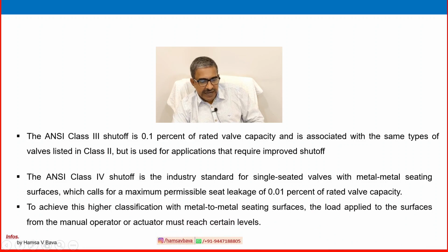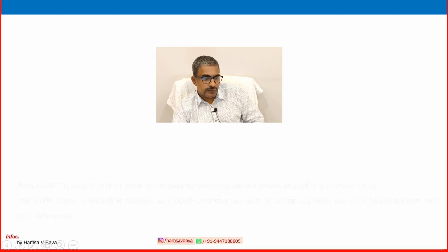To achieve this higher classification with metal to metal seating surface, the load applied to the surface from the manual operator or actuator must be at a certain level. So the actuator concept is also used in higher classes of shutoff classification.